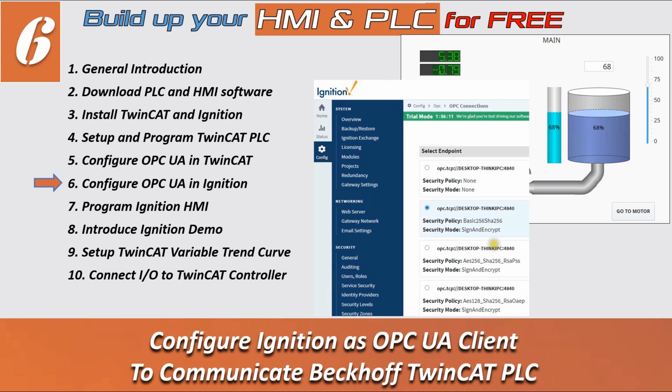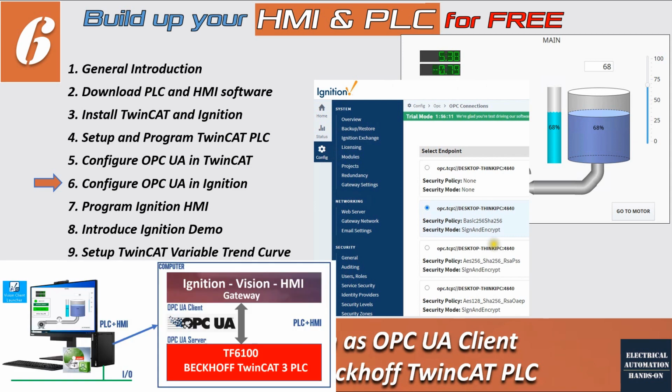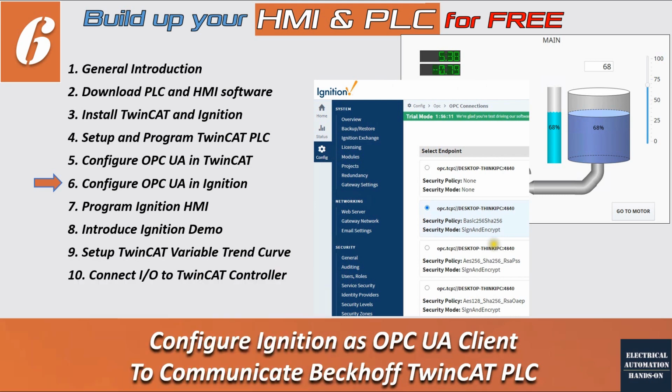In this video, we will discuss topic number 6: how can we configure the OPC UA client in the Ignition HMI system. Basically, we will configure the Ignition side as an OPC client, and as shown on the screen, we will browse the OPC server that is located on my computer. This is the TwinCAT OPC UA server, and in this case, I will also use the security setting.